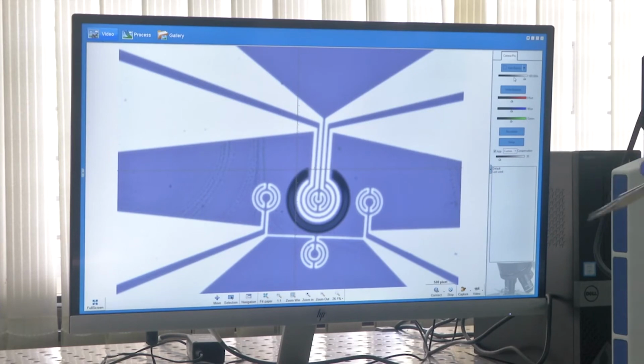Correct? The dark ring-like structure is actually a trench, or a deep hole, that has been made for thermal isolation. Around this trench you can see three structures, right? Three winding structures. These three winding structures are again resistance temperature devices. What are resistance temperature devices? Resistance temperature devices are also like micro heaters, but the difference is that they are not actively heated. That means they only respond to a change in temperature to which they are exposed. They are themselves not heated to a particular temperature.